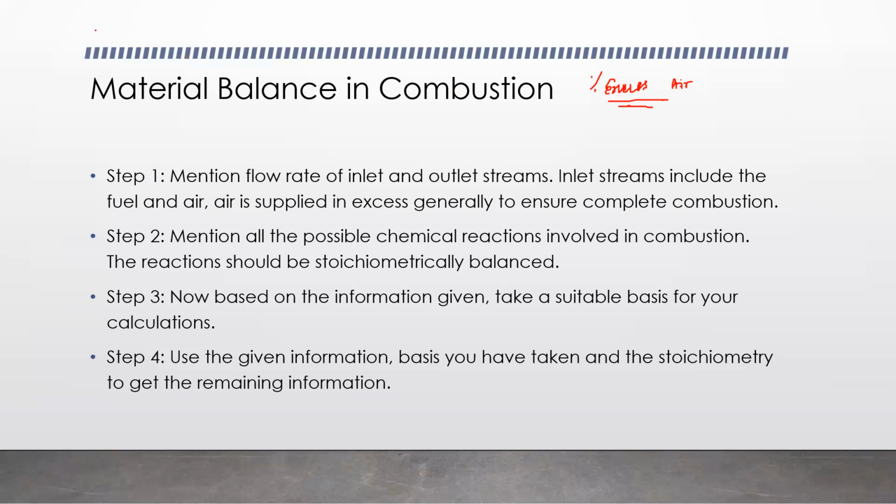So you're going to use the formula that we derived using B. So B supplied is B theoretical into 1 plus percentage excess by 100. So that formula is going to be useful over here when we deal with percentage excess air. All right.